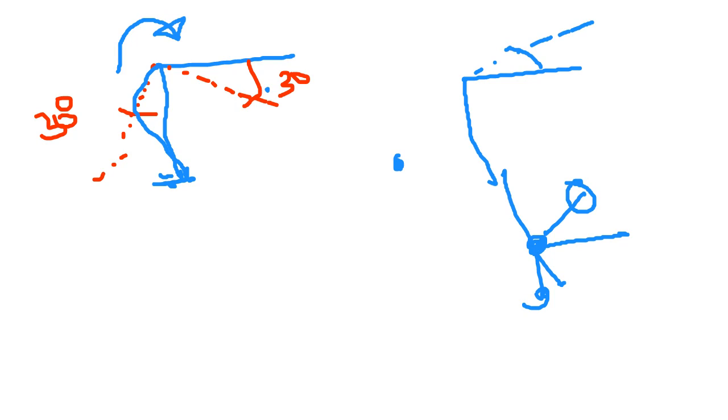Yes, definitely. If the joint is a hinge, there will be no moment transfer, right? But if it is rigid, definitely it will transfer your moment to the other end. That is what we do in moment distribution methods. Then we apply carry-over factors and distribution factors, and then we get the moment transferred to another joint or another section of the joints, right?